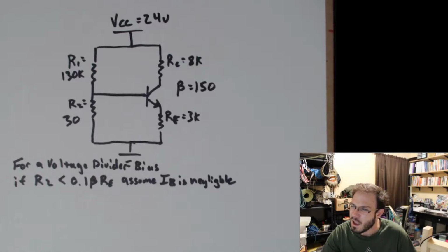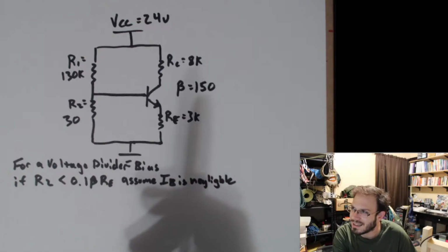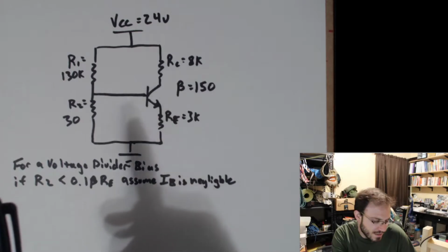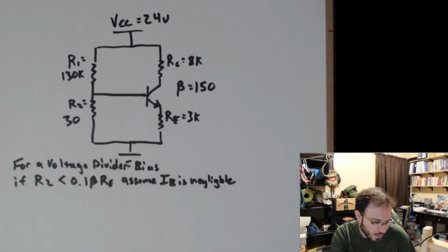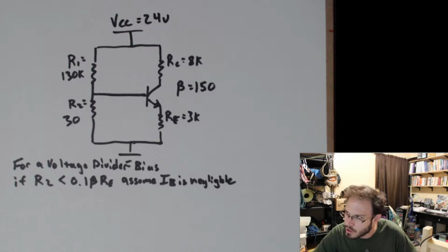And if you're sinking more than, say, 10 milliamps, if you have 10 milliamps or greater going into the microcontroller, then I would suggest having an external circuit to do that, similar to that base bias circuit that we did with a transistor, and we did examples controlling an LED, turning that LED on and off, and in lab we'll also do that as well.